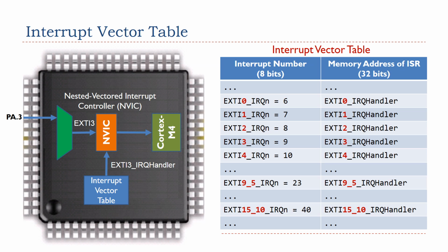EXTI3_IRQHandler. External interrupts from number 5 to 9 share the same interrupt handler, EXTI9_5_IRQHandler. External interrupts from number 10 to 15 share the same interrupt handler, EXTI15_10_IRQHandler.